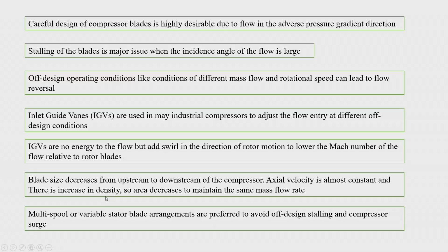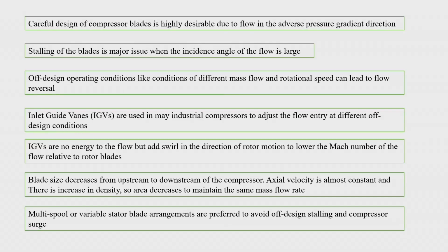Okay. So, there are different options in case of off design catering of the compressor. One of the options is use of a multi-spool arrangement, another option is to have variable stator blades for avoiding the stalling or surging of the compressor.